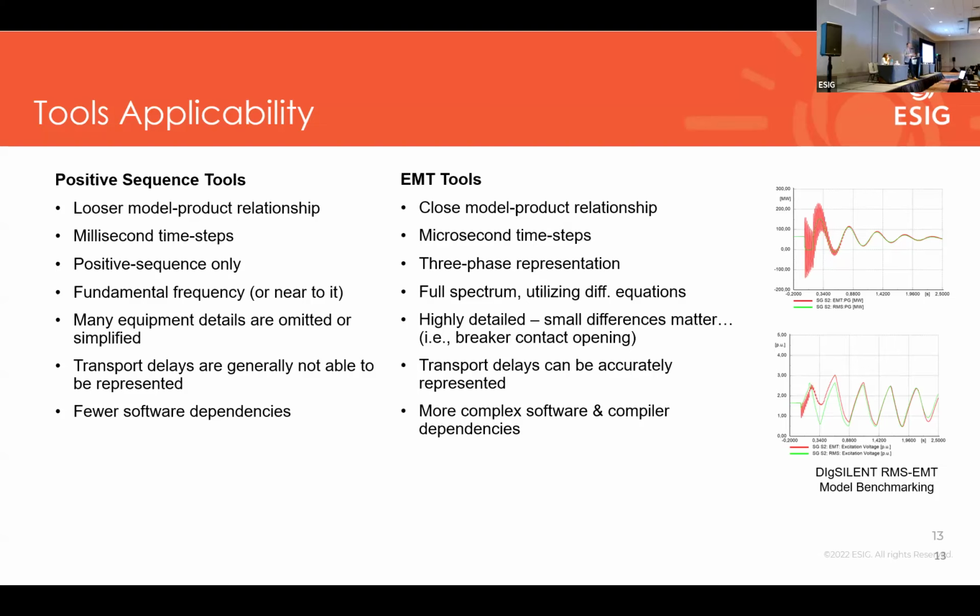The time steps are at the milliseconds level. They're only looking at positive sequence, fundamental frequency, or very close to it. And many simplifications are intentionally made about the equipment to get it to work in that environment. When done correctly, they are very useful and will continue to be so.